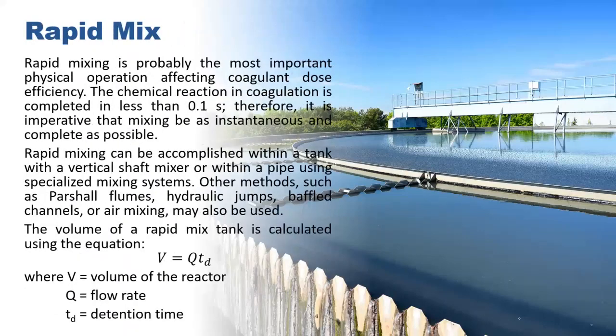On the other hand, rapid mixing is probably the most important physical operation affecting coagulant dose efficiency. The chemical reaction in coagulation is completed in less than 0.1 second. Therefore, it is imperative that mixing be as instantaneous and complete as possible.